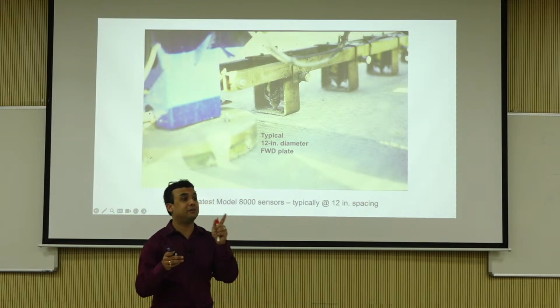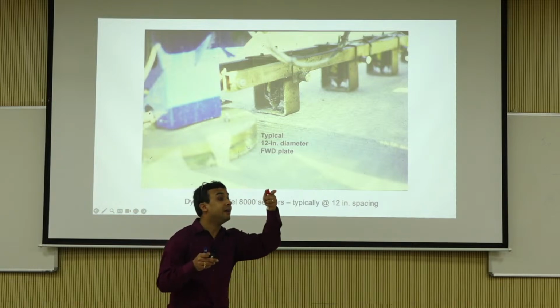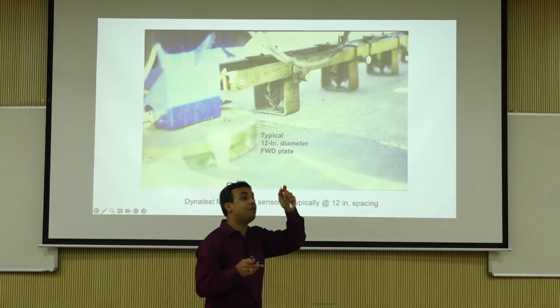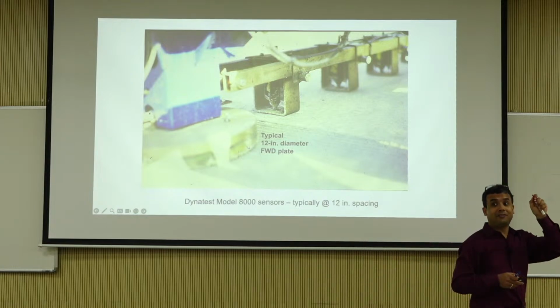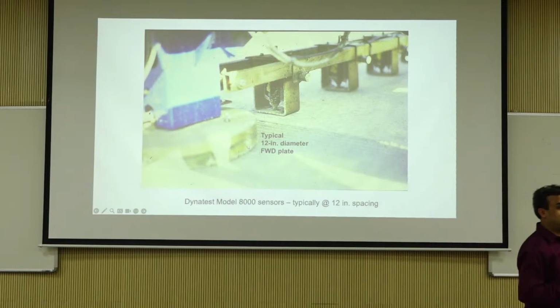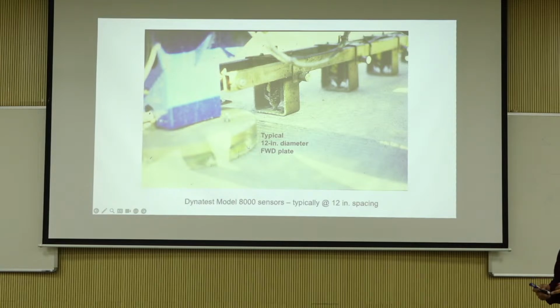They're not acceleration. No, geophones don't measure deflection. Geophones measure velocity, so you have to single integrate them to get deflection. So there are two different types of sensors, right?